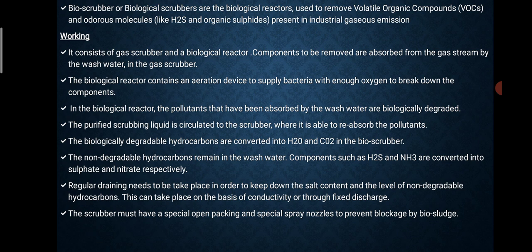Bioscrubbers, or biological scrubbers, are biological reactors used to remove volatile organic compounds and odorous molecules like H2S and organic sulfides present in industrial gaseous emissions.